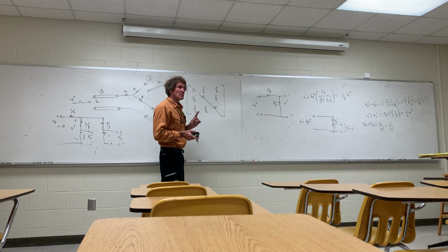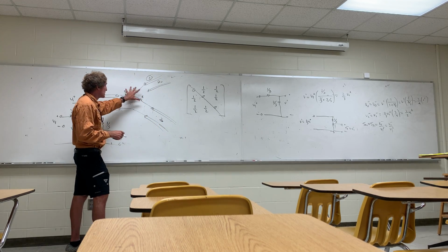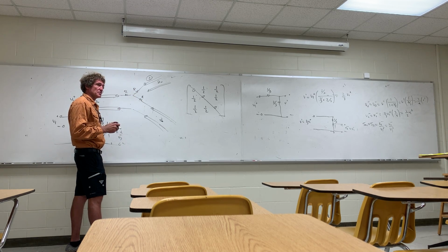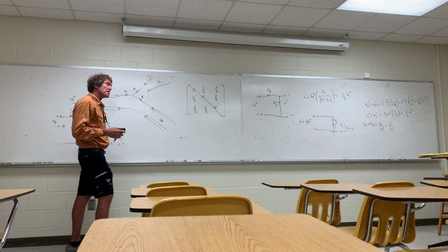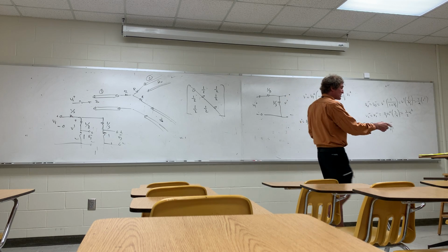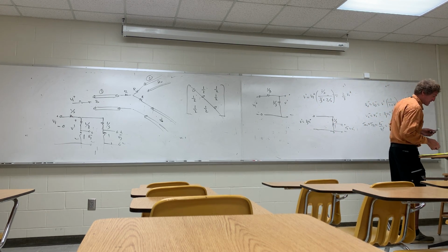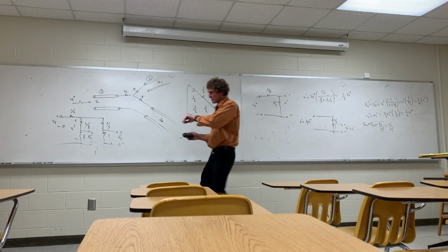Now, the thing you should note is you're losing power in here. If we actually calculate the power loss, you're going to see you're losing a fair amount of power because you're using resistors to do this. You're not using capacitors and inductors to achieve this. A better way to do this for a 2-way split is with something called a Wilkinson divider, and he shows that on top of page 571. I want to just talk about that briefly because it is valuable for this.